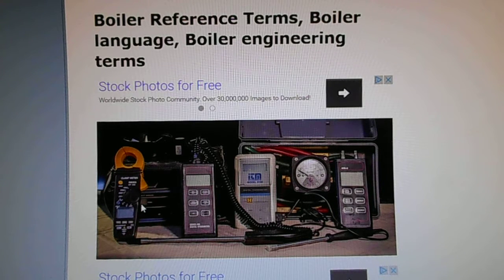Water column. This is a chamber which is connected to the boiler and to which is attached the gauge glass. Safety valve. This fitting prevents the pressure within the boiler from exceeding safe limits. It will open and release water or steam when the pressure reaches the set point. Steam gauge. This fitting term indicates the pressure of the steam within the boiler.